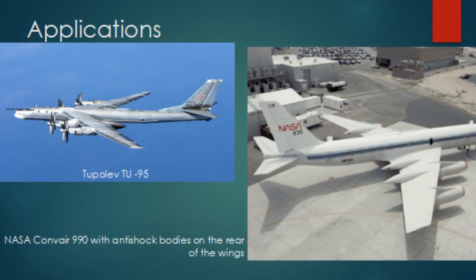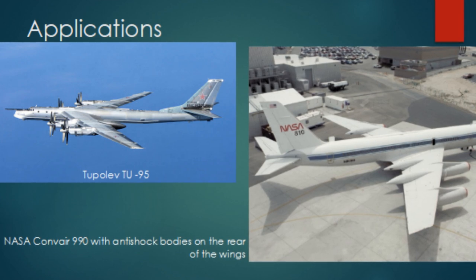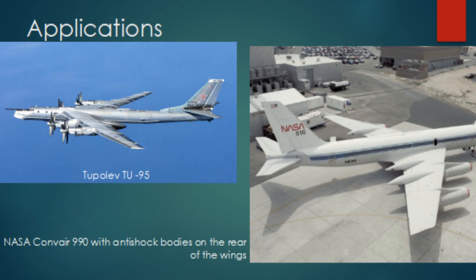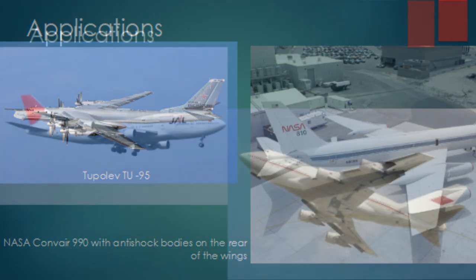Designers at Armstrong Whitworth took the concept a step further in the proposed M-wing, in which the wing was first swept forward and then to the rear. This allowed the fuselage to be narrowed on either side of the root instead of just behind it, leading to a smoother fuselage that remained wider on average than one using a classic swept wing.